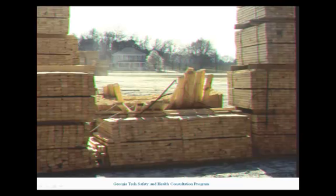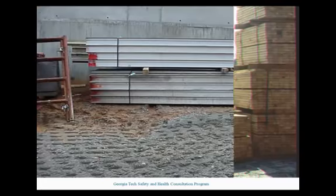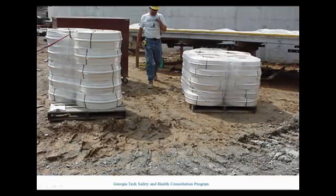All materials should be stored in a secured and safe way to prevent sliding, falling, or collapse of materials. This should take into account the maximum safe load limits of the floors on which the materials are stored. Note how in this first image the wood has fallen when compared to the second image in which the materials are stored properly. Continuing with the general requirements for storage, non-compatible materials must be segregated in storage.